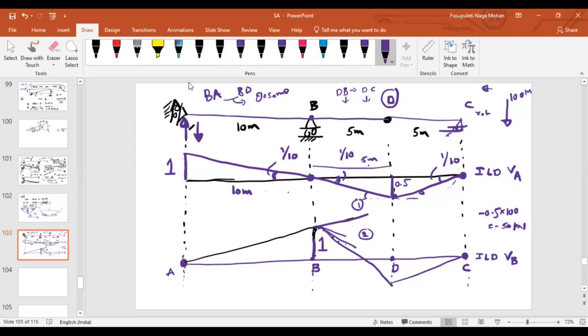No, sir. Now see, as I'm telling you, B is a continuous support. Is it right? Yes, sir. Not a continuous support, it is a continuous member at B, isn't it? Yes, sir. There is a beam like this and we have just placed a support below it. That means whatever the slope of the connected members at point B, should it be the same or different?